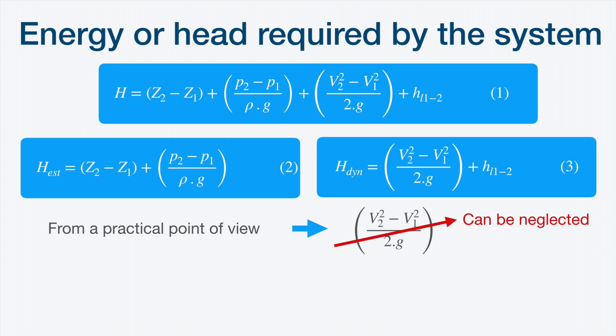If you want to calculate the head more accurately, you cannot neglect it, but in practice, it doesn't have any great influence on the final value of the head when dealing with pumps. But anyway, if you want to consider this term, please do it. But in practice, it is not necessary.